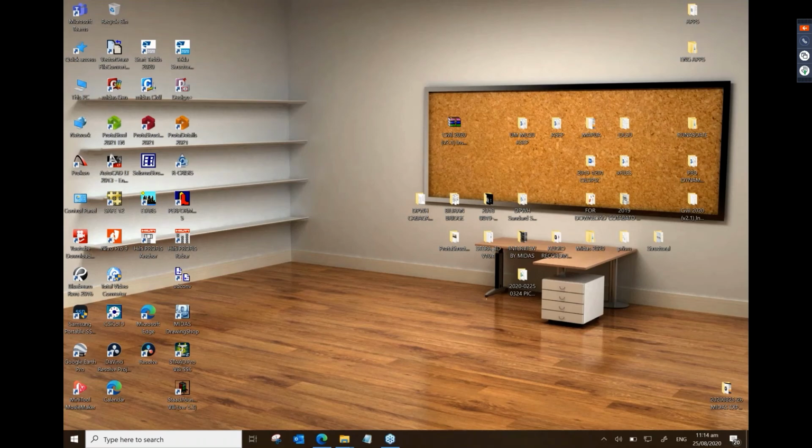Let me just give you these scenarios wherein you need to do performance-based design. Number one, definitely for an existing building, especially if that building happens to be a critical or essential building subjected to ground shaking, it's recommended that you do the performance-based approach.